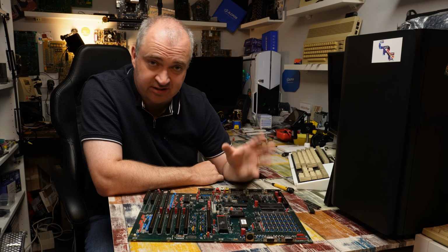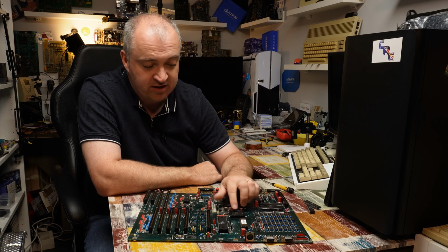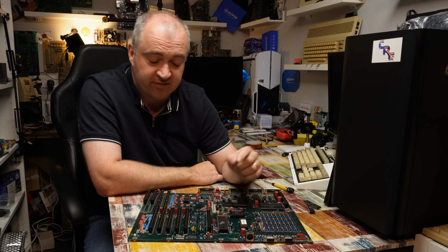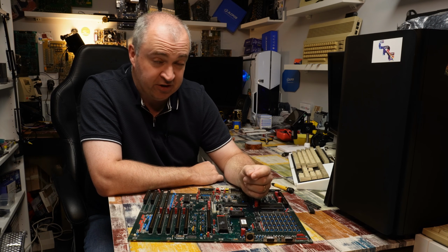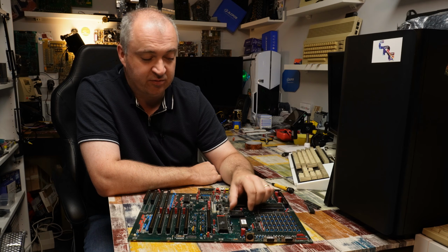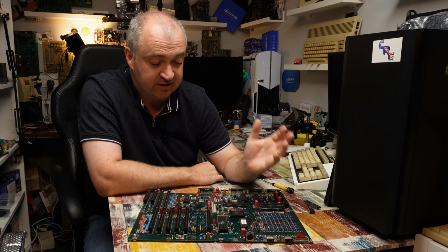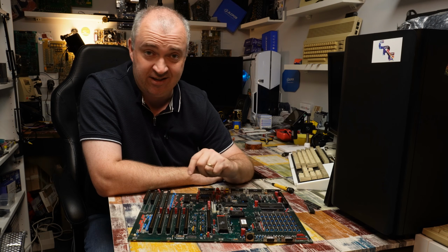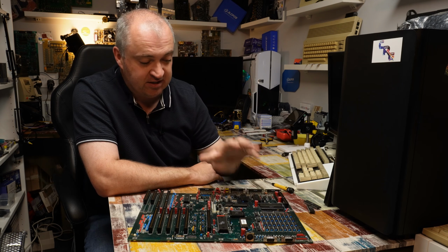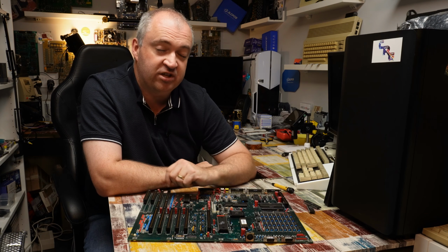You can build an adapter to fit an 8375 and give you 2 meg of chip RAM into the socket for the 8372A, but I've done that before here on the channel. It's not the easiest thing to build. In fact, if anyone who's seen that video, you will know how much I struggled with it, and I swore I will never do one of them again. So this machine is sticking with its 8372A and 1 meg of chip.